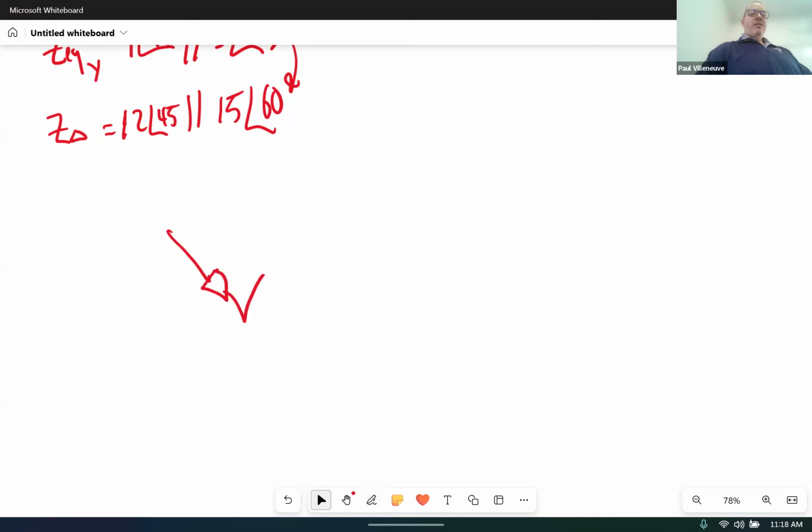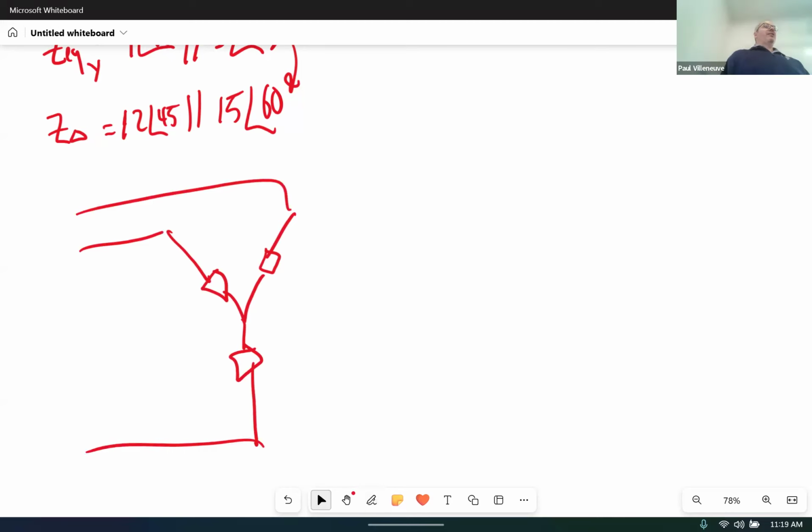So how would you ever be able to connect them? Because remember, these are 3 separate connections. And remember, when I say equivalent impedance, that's a Thevenin equivalent. If I've got a source looking at that over there, how can I add these 2 in here? They're not connected. So there's no such thing as a 3-phase equivalent impedance. There are single-phase equivalent impedances. Each one, you have to have 3 of them to make it work.